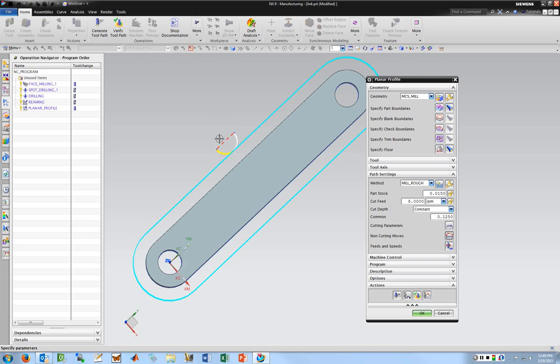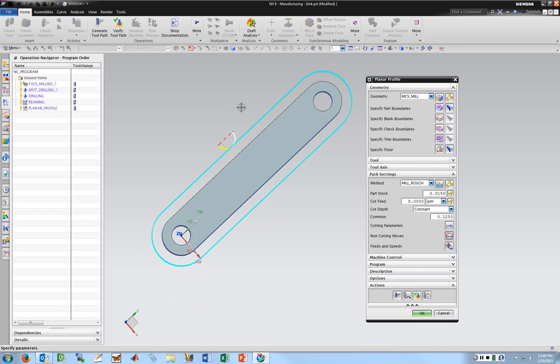But you also have to have space here. If this is where your nice Kurt vise is, your nice Kurt vise is going to be machined, which is probably not going to end well if you use a 1/2 inch high-speed steel bit to machine a Kurt vise. That'd be interesting to watch, but I don't want to see it. So make sure you've got clearance over here. So that looks good. I've got tool paths.